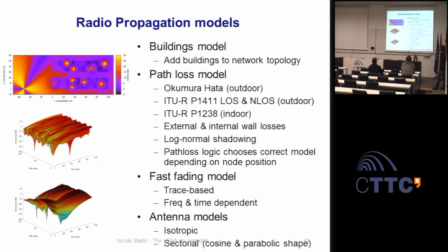Now, for the rest of the presentation, I will deal with the specific parts of the LTE model, and the approach will be bottom-up, going from the lower layers, from the channel to the physical layer, up to the LTE protocol stack, and then to the core network and so on. So, from the point of view of channel modeling, the radio propagation models that are used inside the LTE model, most of them have been developed inside the LENA project, but they are actually not specific for LTE, and so they have been contributed to the ns-3 project, and you can use them even with other wireless technologies such as Wi-Fi, for instance.